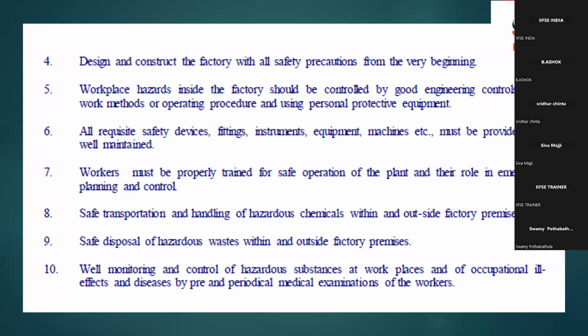Yeah. So we are talking about hazard operability study. Why do we do it? Hazard operability study is basically done to see the design deviations. Design deviation means, for example, my factory has 10 reactors. The flow has to happen in such a manner that once the chemical reaction happens in reactor 1, it goes to 2, then to 3, and finally comes to reactor 10.